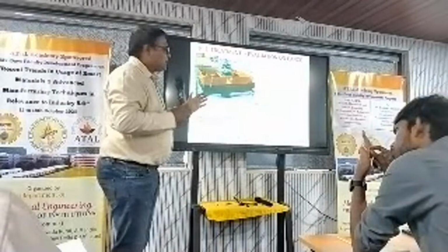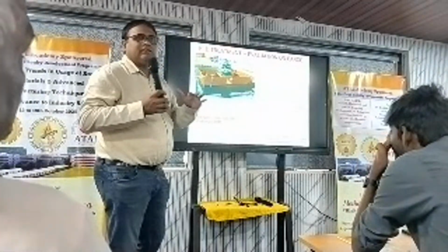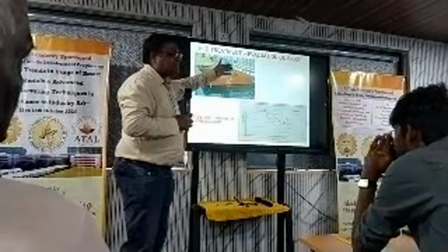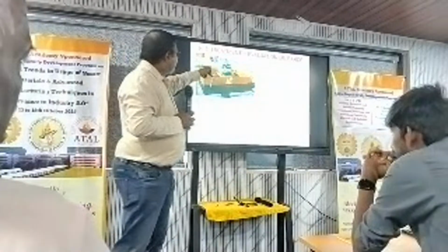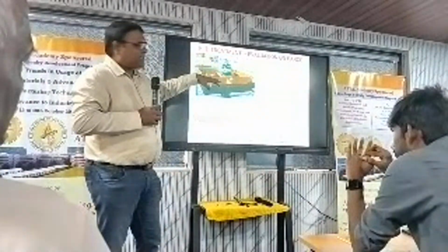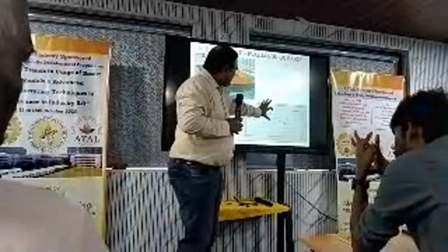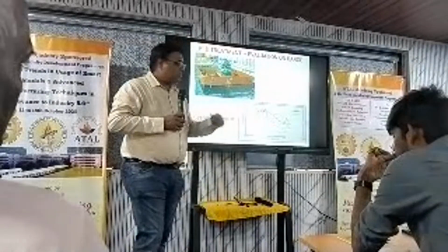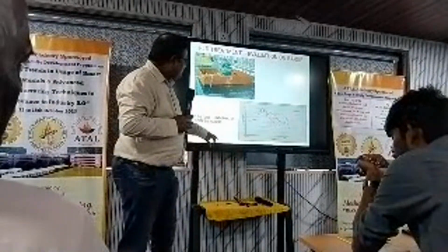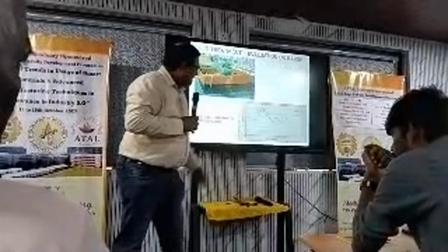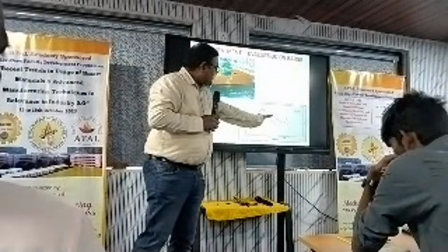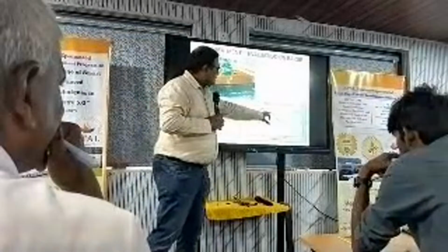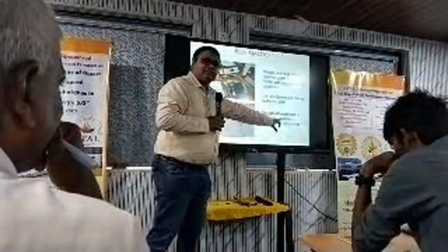This is one of the small barges. Before going to ship experiments, we have to go for laboratory tests, where some barge is there. This is the compressor which creates the vibrational energy, and we have to measure the vibration levels before and after the application. There is a drastic reduction of the vibration energy, around 10 dB, 20 dB, for a broadband spectrum up to 10,000 Hz. This is the before vibration level, which is higher, and this is the vibration after applying FLD.